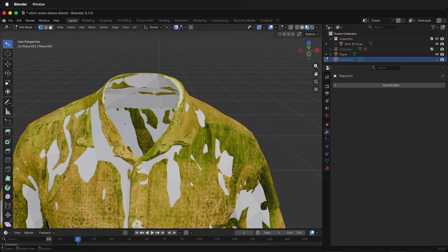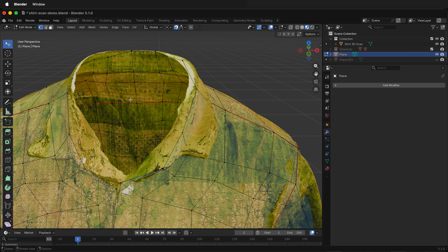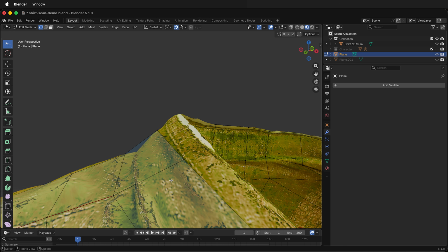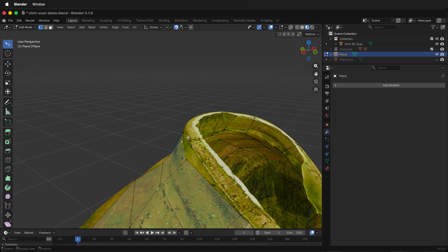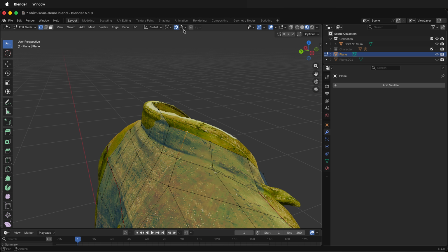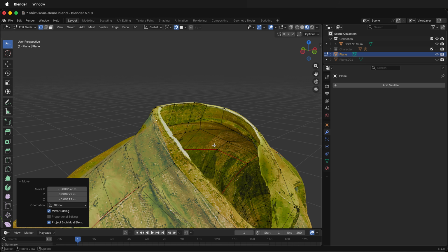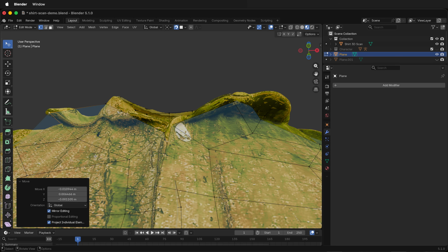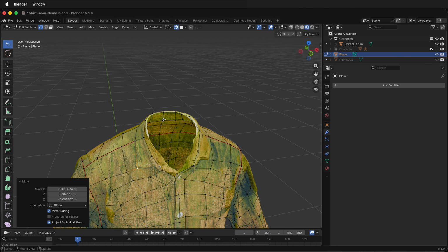So if I bring this plane back, and then I bring the 3D shirt, I can put all of the pins, rather than on the outside, I can use this inside curve and just kind of match that. Because this is the closest thing you're going to get to the actual collar stand. But this detail here doesn't matter until you actually are ready to move everything at the very end. Because once you actually snap things together, they're going to pop right back up to that collar. You see how that pops back up? So really the collar is the last thing to do.